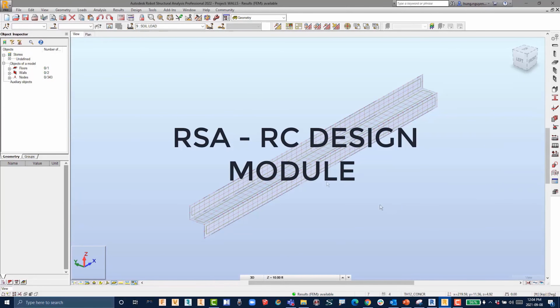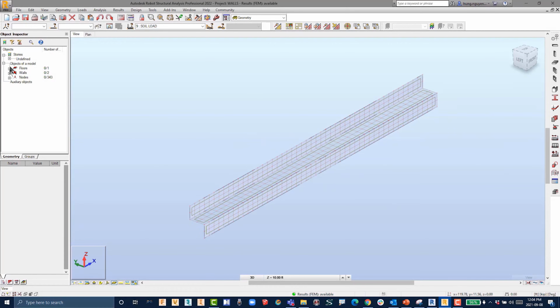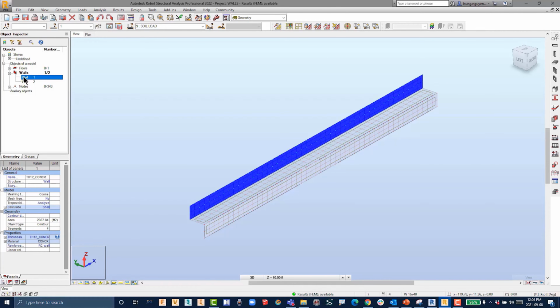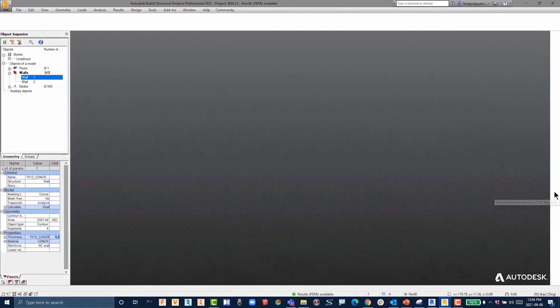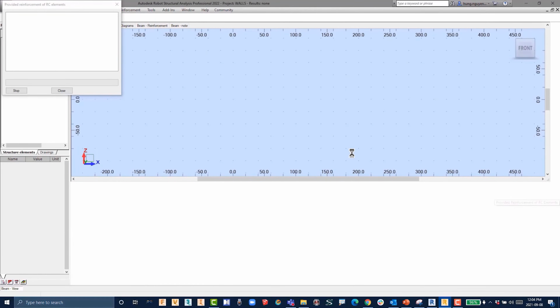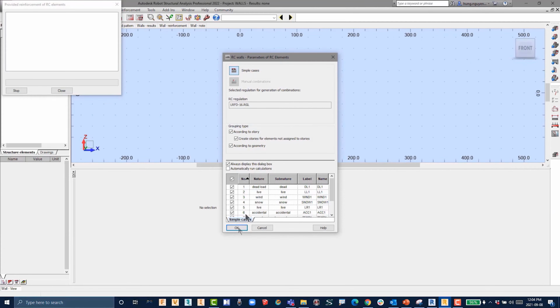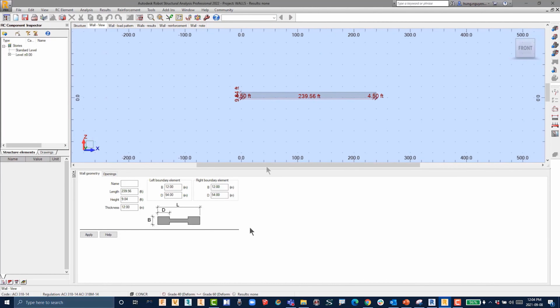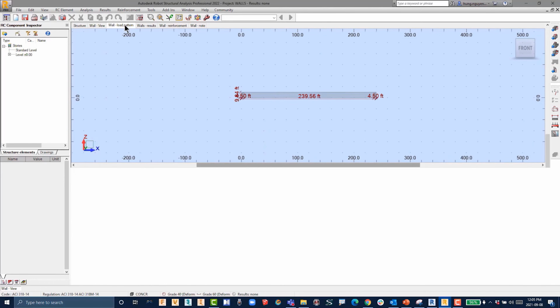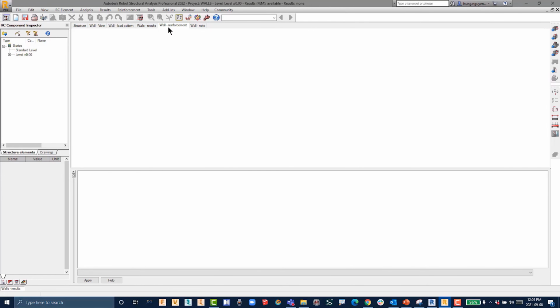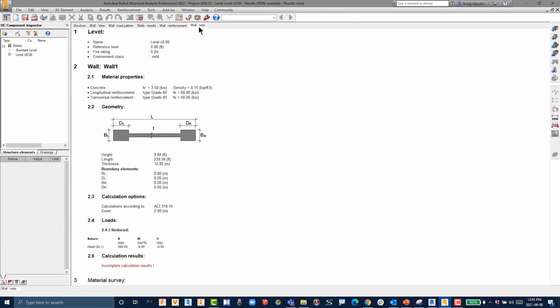ACE also has a very nice reinforcement concrete design that calculates and recommends provided reinforcement for concrete. So let's take a quick look. With the retaining wall still open, I just select one of the wall number 1, and I'm going to send it to the reinforcement calculation module. I'm filling it up, just simply calculate based on a simple case, and on the interface, you can see wall reinforcement, wall node, and the complete report that can be generated out of one of the nodes.